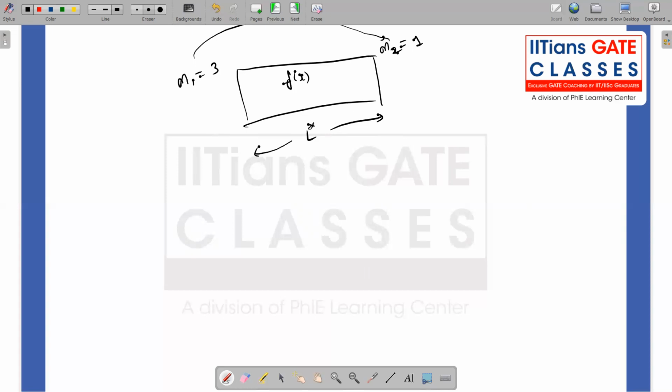That's the length of the duct needed to make sure the friction is bringing the flow from supersonic to sonic condition. So this L star can be varied depending on the empirical relation f of x, whether the flow is laminar or turbulent. This is a much more involved problem.